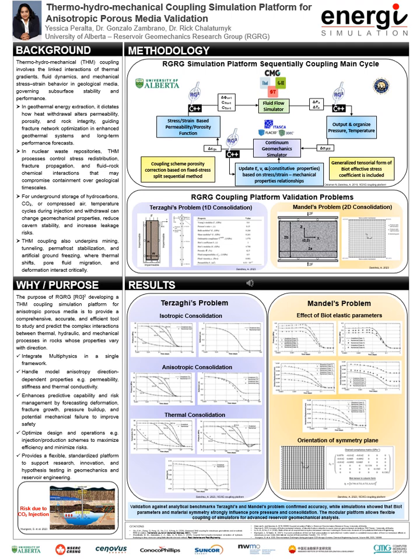For this case, we analyze 5 cases. The first one, baseline horizontal isotropy, meaning the isotropy plane is horizontal, representing the layered rock. The second case, incompressible solid grains. The solid skeleton is assumed incompressible, increasing Biot coefficients and affecting pressure buildup. The third, reduced solid stiffness. The solid matrix is half as stiff as in the base case, showing how weaker rocks deform under load.